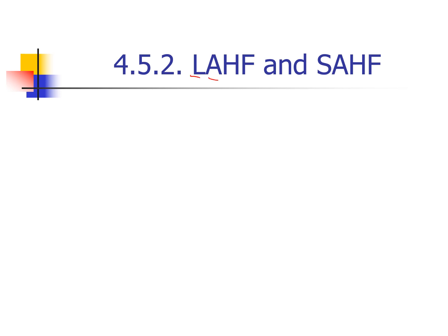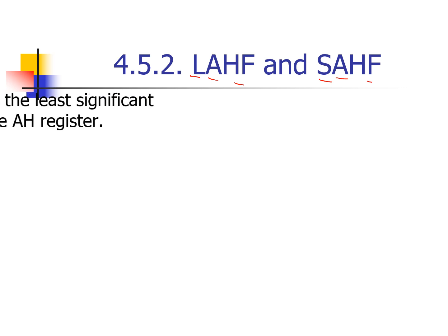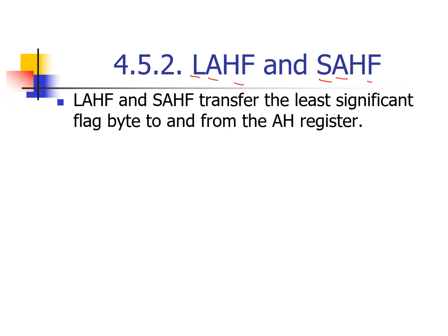Load AH with F, store AH in F. Good. It transfers the flag bits, the flag byte, into the AH register, the higher portion of your AX.